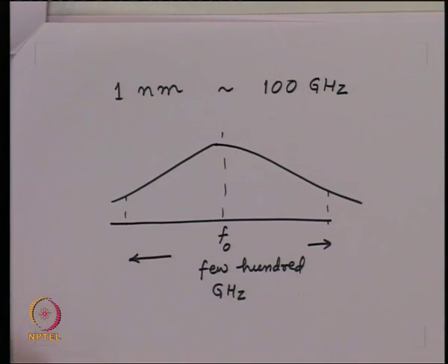So now essentially we take this fact into consideration, that the optical carrier has a spectral width which is very large compared to the modulating signal frequency, and as a result the side band will not be clearly visible. We will come back to this point a little later, but at this point it is very clear that when the signal is transmitted on the optical fiber, a simple understanding which we have for radio frequencies will not be applicable in this case.